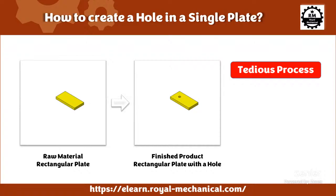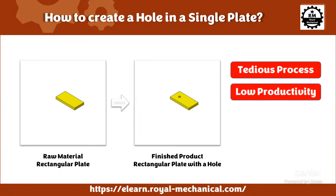What you observe is that this is a very tedious process. We need to mark, then scribe, then punch, then hold it in the vise, then drill, and then take it out of the vise. So a very tedious process. Because of this, it is going to be a very low productivity activity, especially in a mass production environment.